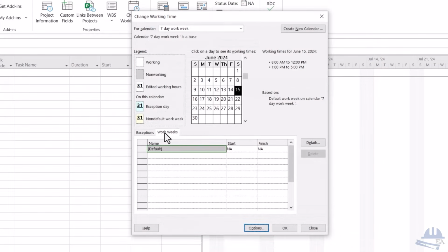So over here there is other thing that you have to do. This is exceptions tab, and over here you put the exceptions date. So all these days are working days and exception days are the non-working days. For example, if there is a holiday, let's say that a new year is a holiday, right? So we'll say new year, and it starts when?